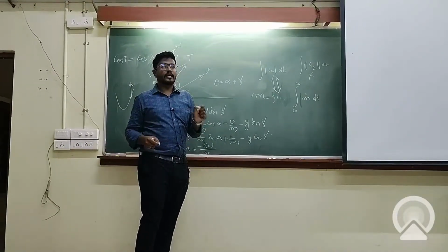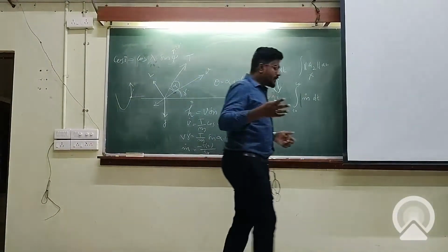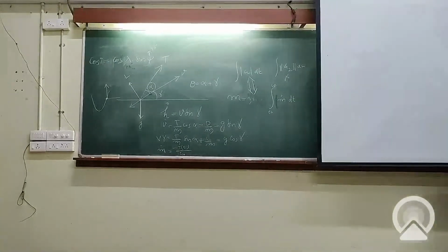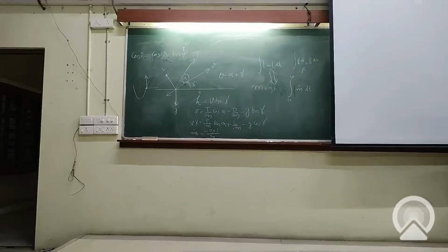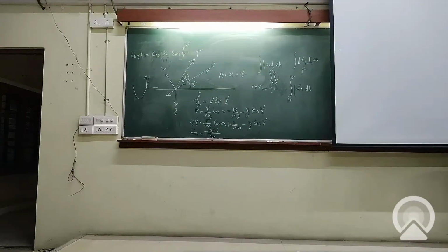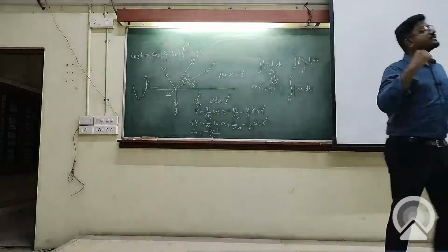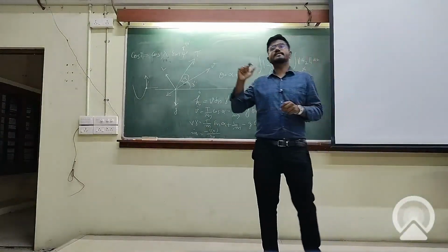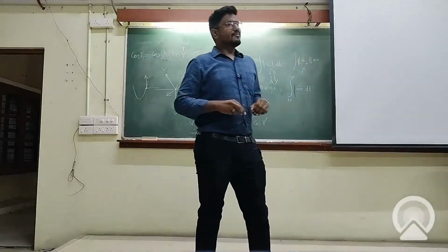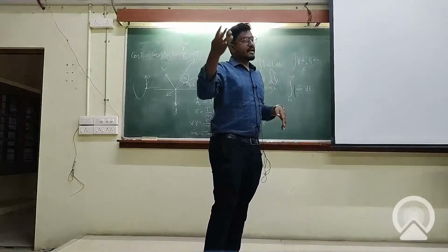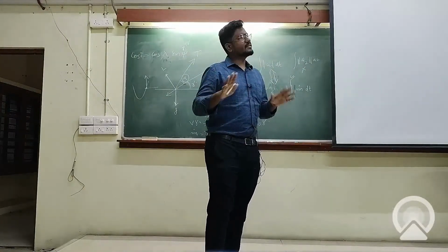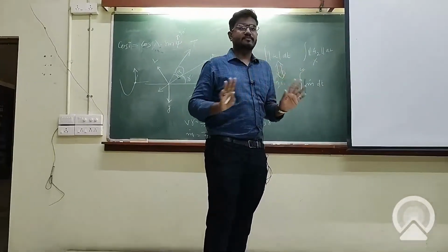It is determined by the inclination. Then again, the argument of perigee is also determined by the targets. I mean, the injection phase, that is velocity or altitude, normally doesn't mean anything. It doesn't describe the orbit. It just describes where the spacecraft is in the orbit. We are not really concerned where the spacecraft is in the orbit at the time of injection. As long as we get the orbit, it is fine.